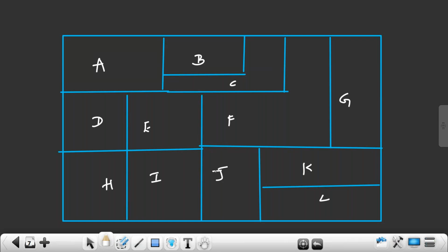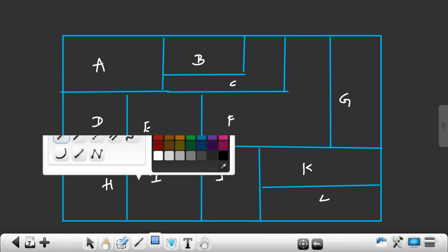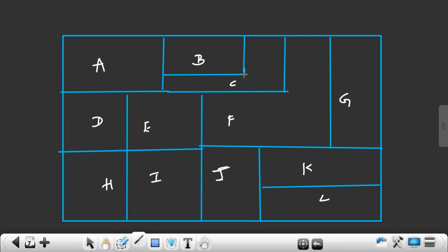So each block will be having a cell count of around 10 lakh to 30 lakh within that range. Every block will not be having same cell count. It may vary between 10 lakhs to 30 lakhs. They will divide the entire chip into different blocks, right? So first we will start physical design of each block. There will be separate netlist given for each block. So A will receive his netlist and B will receive his netlist, C will receive his netlist.